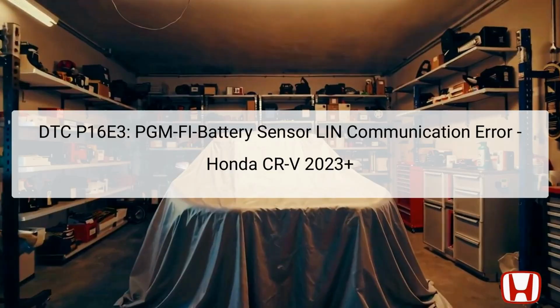The DTC P16E3 indicates a communication error between the Powertrain Control Module (PCM) and the 12-volt battery sensor over the local interconnect network (LIN). The PCM requires accurate sensor data for effective vehicle operation, particularly for managing battery usage and ensuring reliable engine performance.